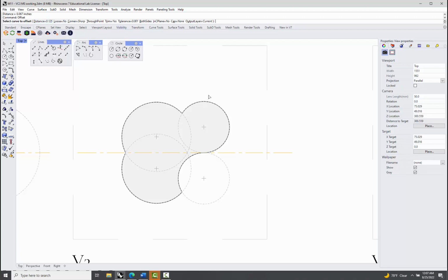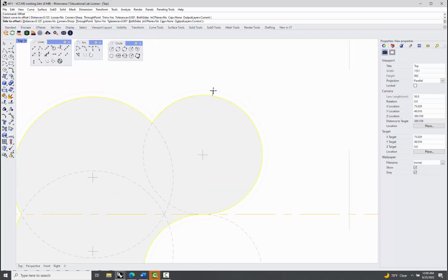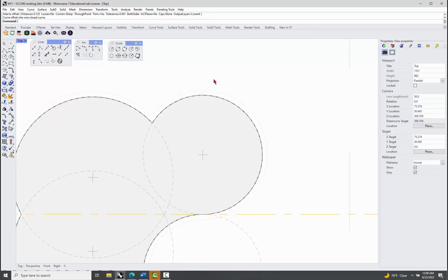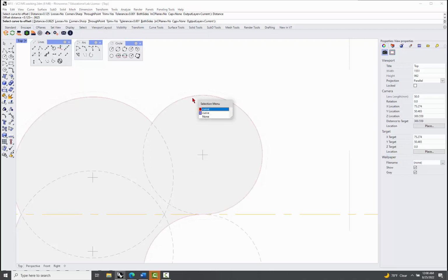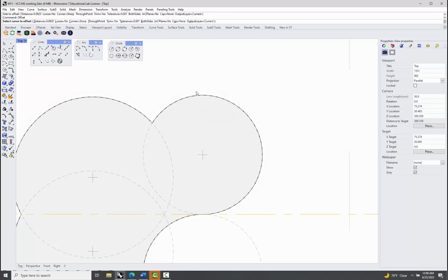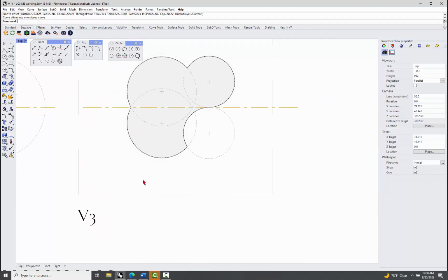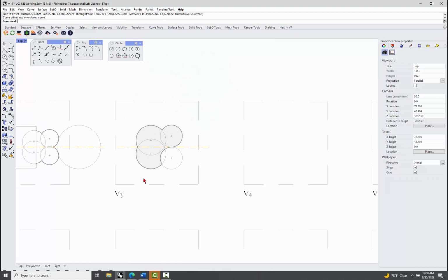So I'll come in and select the curve, right, and offset that to there, and then I'll offset, maybe this is 0.0625, right, and oops, don't really want that curve, I want that curve. So now you kind of have this little double offset curve that gives it a silhouette. So, just something to go in and work with.